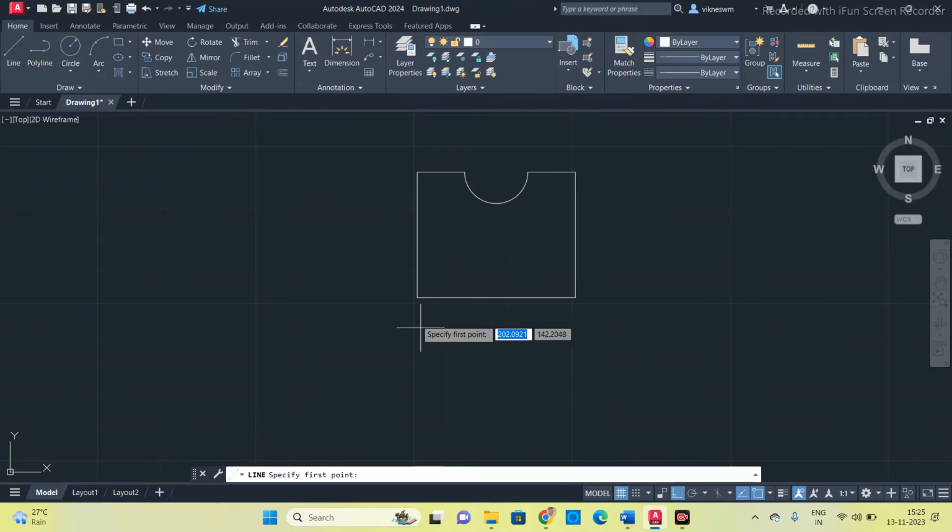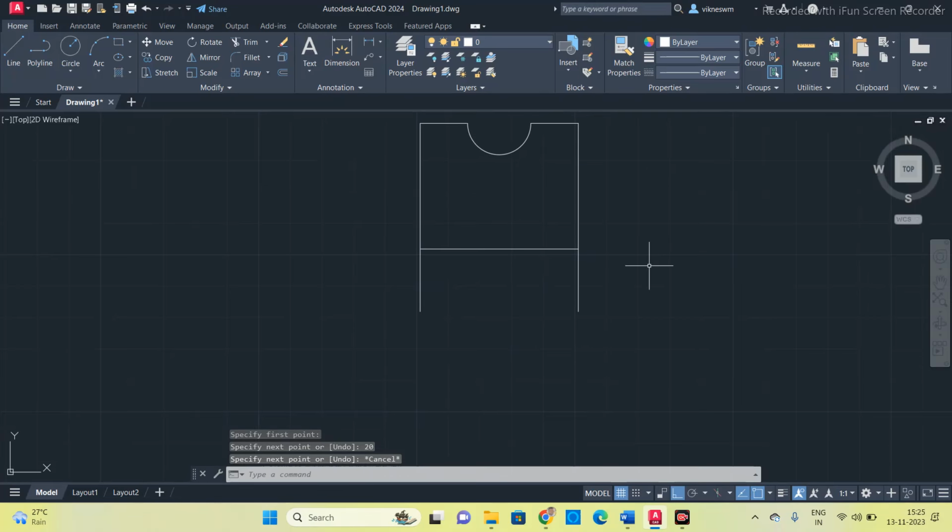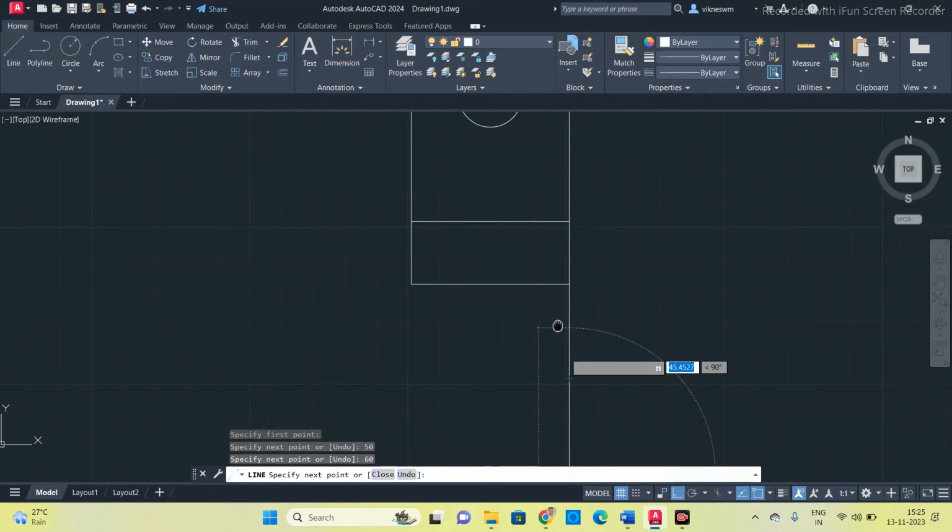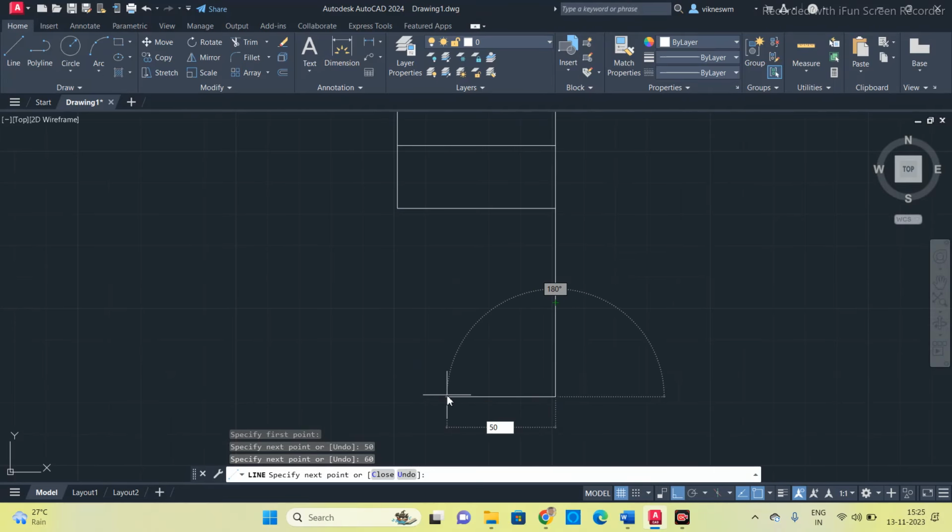Before drawing the top view, we have to take the reference from the front view. So I'm drawing this line for 20 mm. This is just a reference line to start drawing the top view. Now I'm going to start my top view from this point. Lengthwise there is no change, which is again 50 mm, similar to that of the front view. Okay, 50 mm. Now widthwise it is 60 mm. Again this 50, and then again close the rectangle.